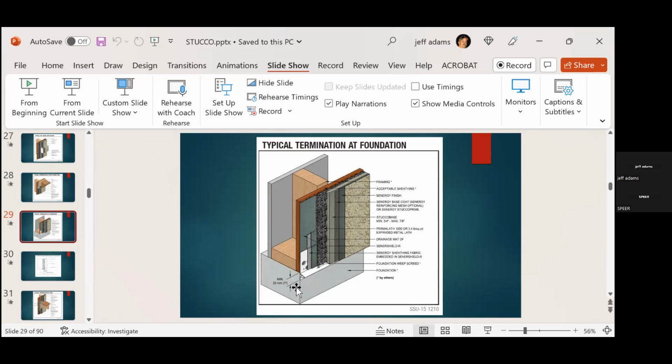It's showing you here that your minimum overhang is 1 inch, okay? This is really not a very good detail because a weep screed is measured from the top of the flange to this inside corner here, okay? So that is a 3.5 inch weep screed. The total length of that weep screed to that bottom turn down flange down here is going to be roughly about 4.5 inches. So per code, our siding has to overhang by 1 inch.